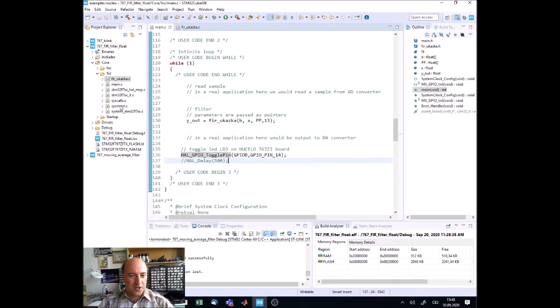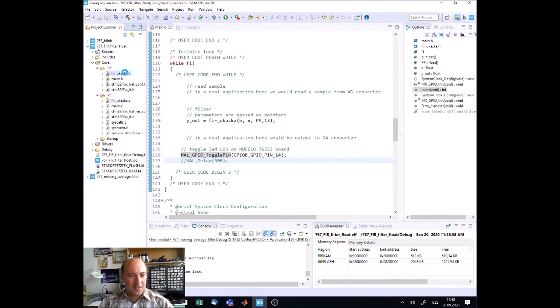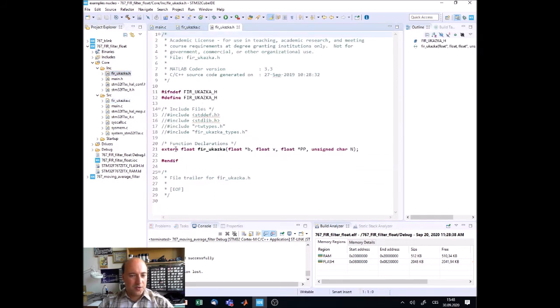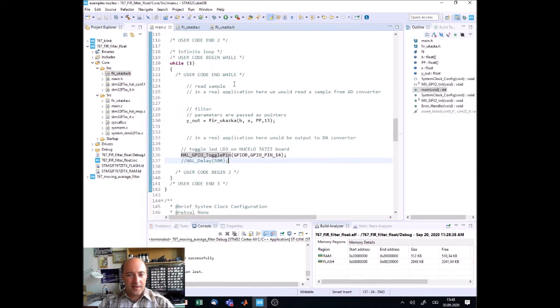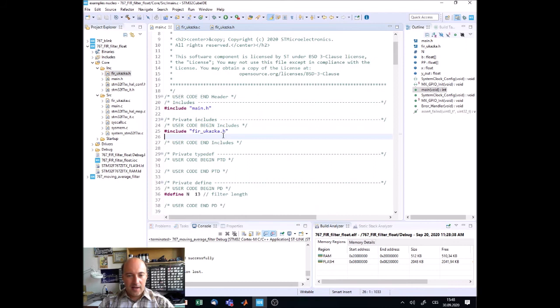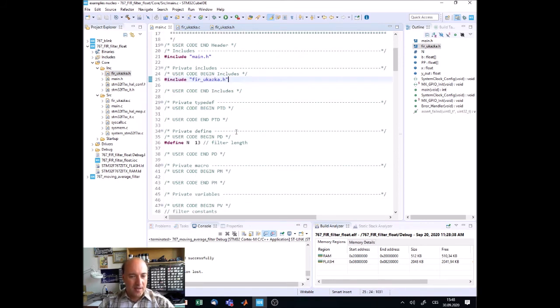And when I have generated that from MATLAB, I got this C file, and I got this H file. So this is the header file for the function. Again, slightly modified with this star and with this star for the pointer.